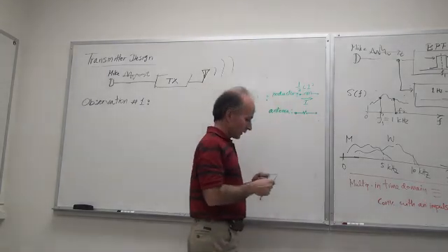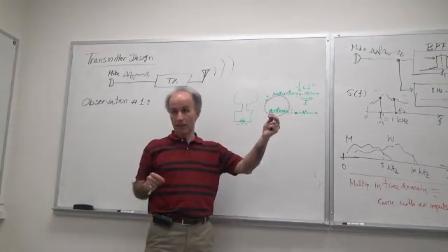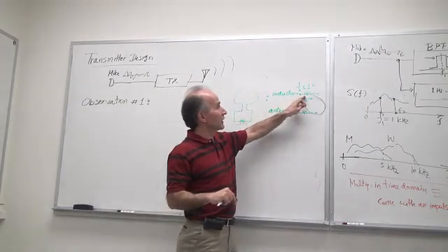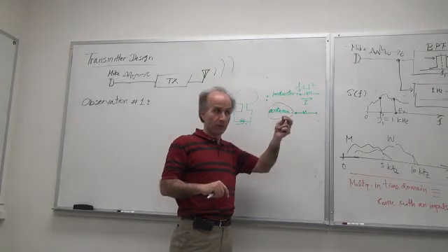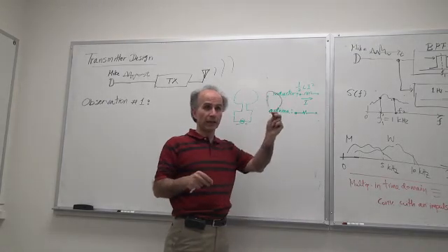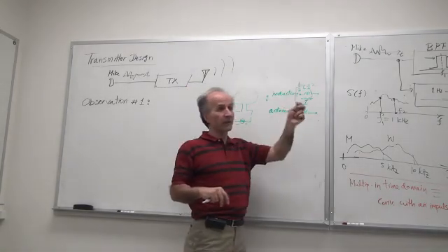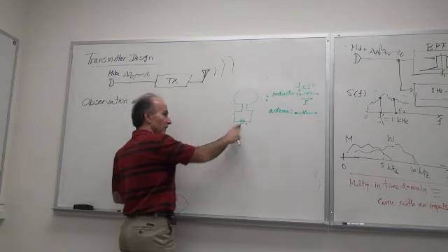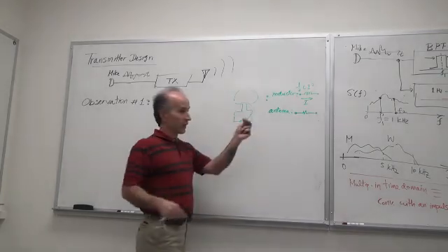A good inductor stores energy. So then the question is, how does this structure decide whether to behave as an inductor or a resistor, or a mini antenna, right? Under what conditions does this loop decide to store energy and not dissipate any, or radiate it completely and store none? Okay, so that's the question. Does anyone know the answer? So we have the same loop, and it can have two very different roles. Well, the way this loop decides is based on the wavelength of this signal. This signal is an AC signal, a sinusoidal signal, a certain frequency, therefore a certain wavelength. Based on the wavelength of that signal, this loop decides what to do.